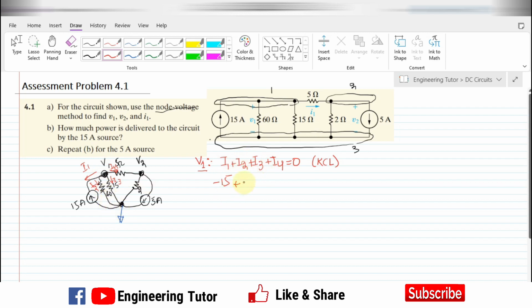So the potential difference here is basically V1 minus 0 divided by 60. This is the potential difference divided by resistance, which is equal to I2. Similarly, the potential difference at the third branch is V1 minus 0 divided by 15, plus I4, which is equal to, again, the potential difference. Now the potential difference is with respect to V1 minus V2 divided by 5, and this is equal to 0. So let me move this minus 15 to the other side.